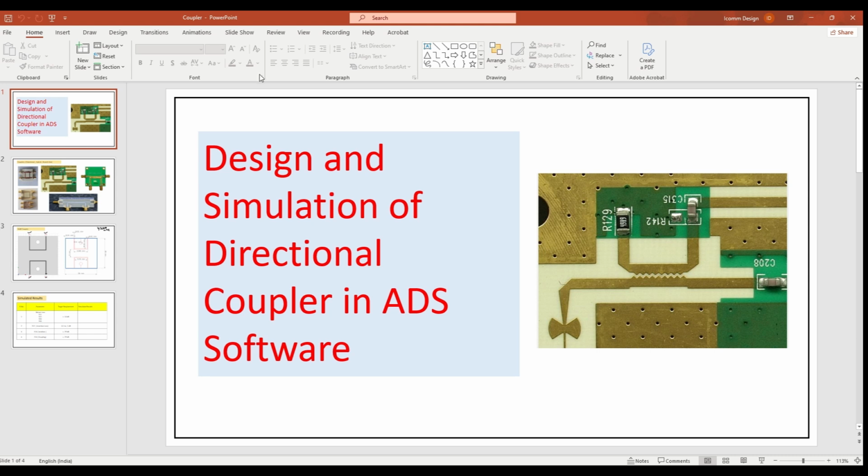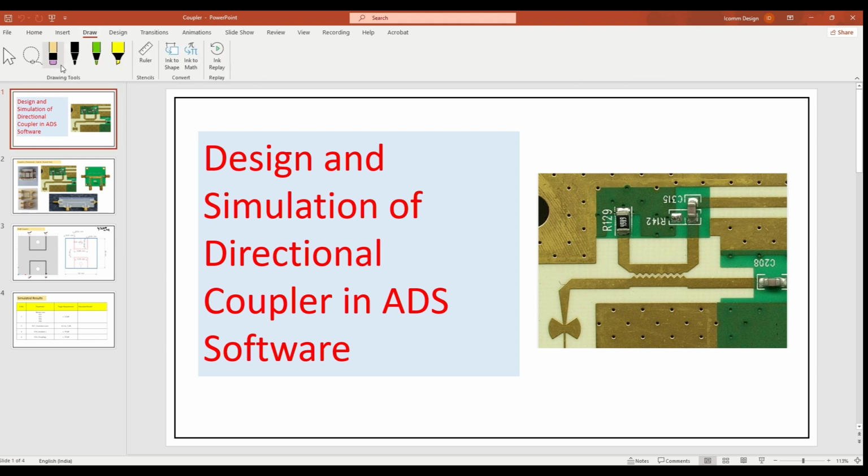So where do we use this directional coupler? Generally we use it whenever we have to couple some power for testing, as a pilot signal or a calibrated signal. We try to reduce the power of a signal by putting parallel coupled microstrip lines in the same format, for example, like this. You give input from here and take output from here. The incident power which is transferred from here to here is the coupled power, which we are trying to take.